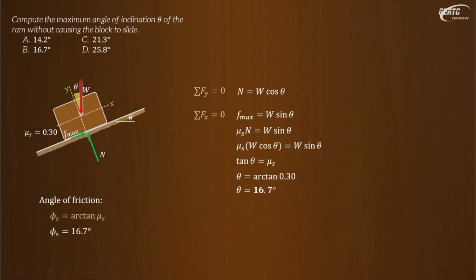You can imagine this: if you want to know the angle of friction between two contacting surfaces, you can incline the surface slowly, and the angle at which the body starts to slide is the angle of friction. This is a very important value for knowing whether the block will slide or not in a problem with this kind of inclination.